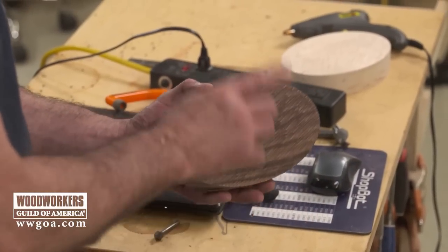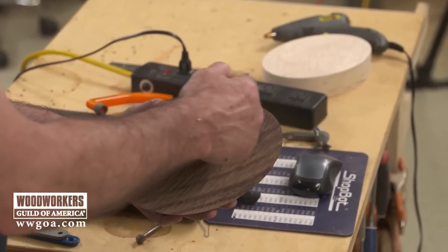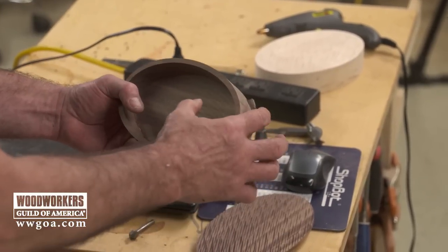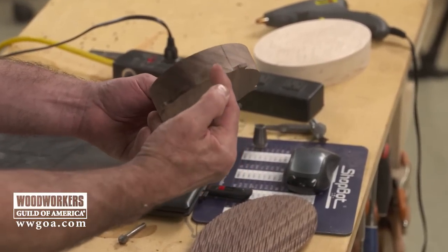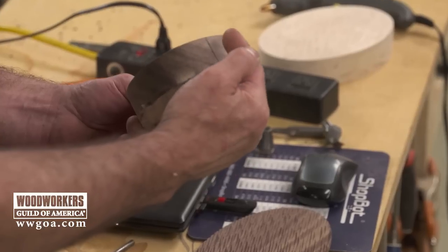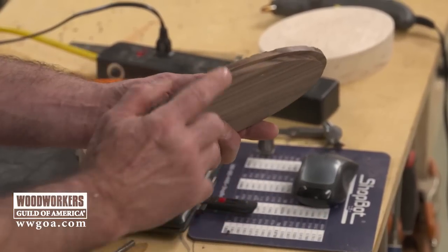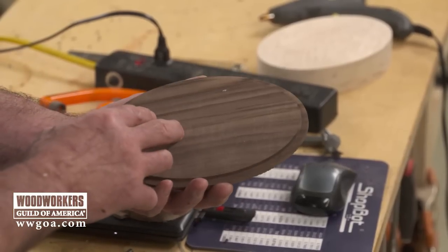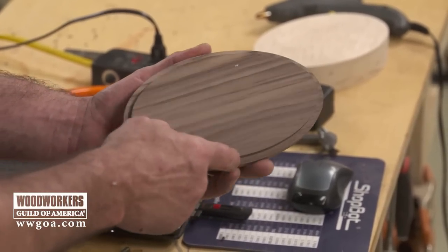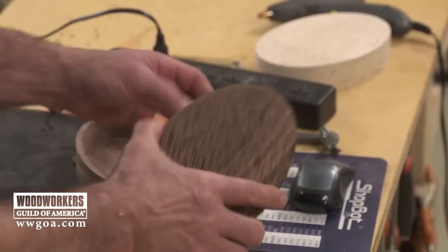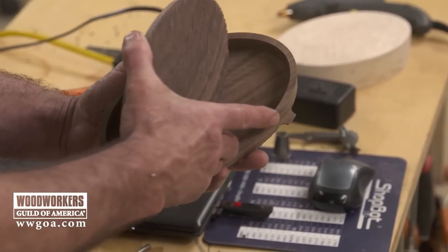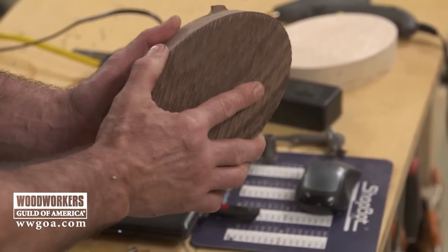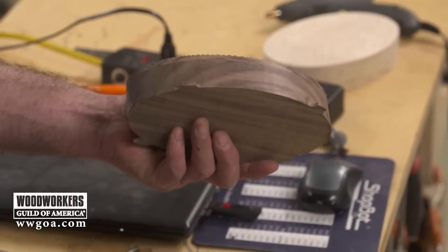Here's our box. Now what I did was, went to the bandsaw and I cut the tabs on the bottom of the box. I left the tabs sticking out a little bit, so I cut them proud on the bandsaw, then went to a sander and sanded the tabs off. The lid, then, I took to a router table and with a 1/4-inch rabbeting bit, cut that rabbet. Remember how we programmed this. We have a just under 1/4-inch wall thickness, making those two parts go together.